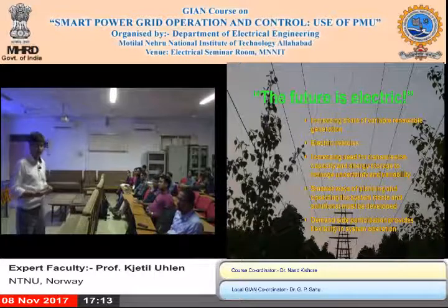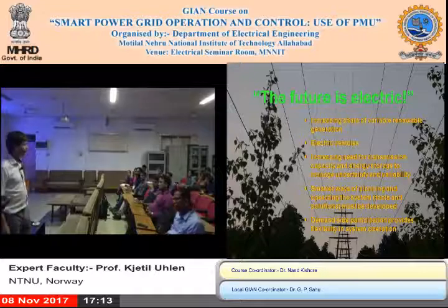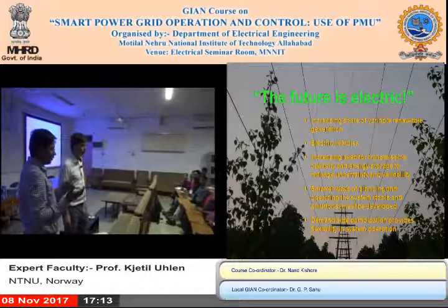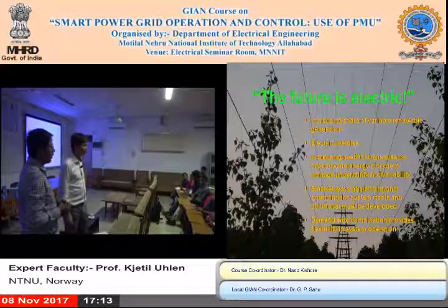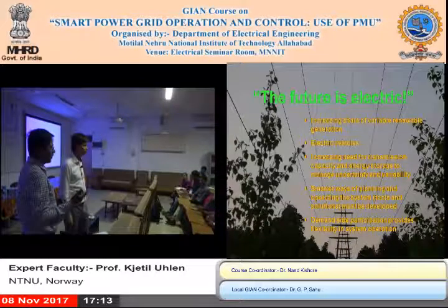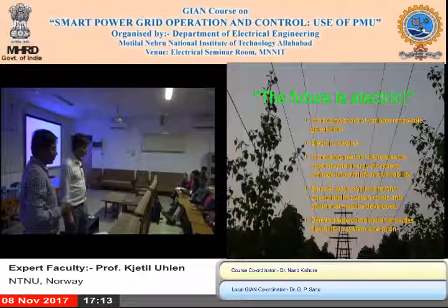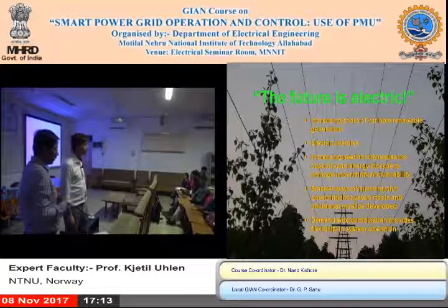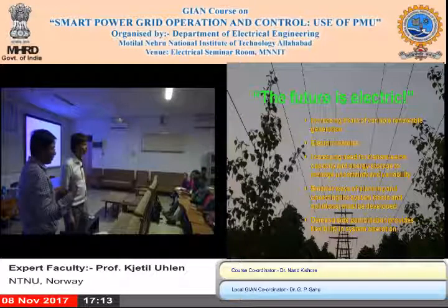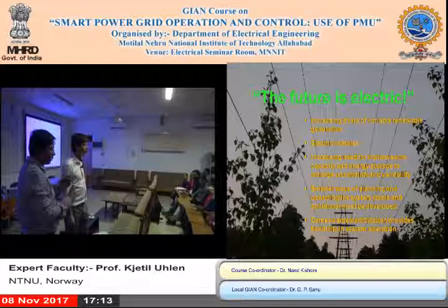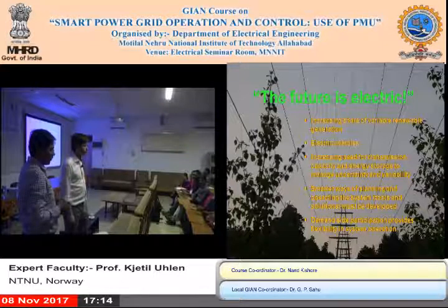Maybe, yeah. Because with the PMU, it's the information about the voltage angle. And then from the voltage angles or the current angles, you can estimate other state values. Because what I understand, frequency you cannot just get directly from the PMU. But from the angles, you are able to know the frequency information.